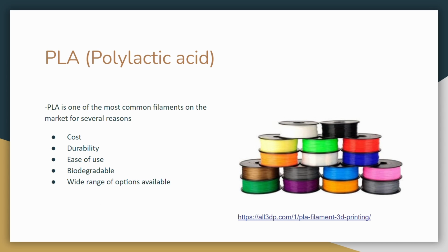One of the two most popular filaments in the industrial and hobbyist markets for simple FDM style 3D printing is commonly referred to as PLA filament. PLA is a very cheap material which makes it accessible to all consumers. With its high surface finish and reliability when coming off the print bed, this makes it a great choice for rapid prototyping applications.